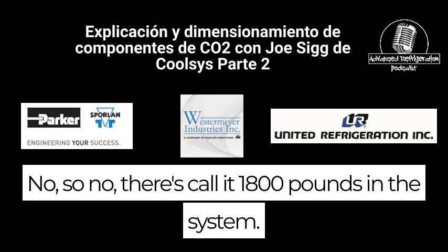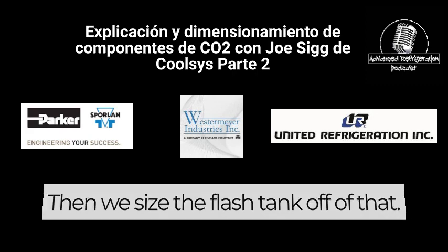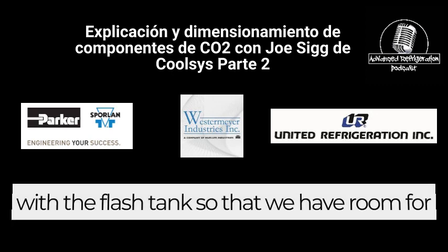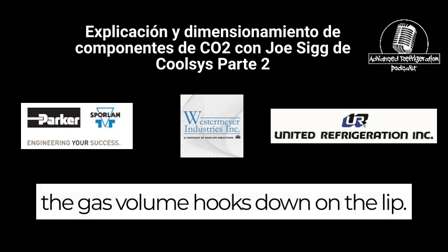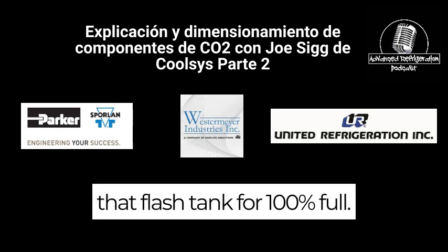No, there's 1,800 pounds in the system, and then we size the flash tank off of that. We know that we want to be roughly 40% oversized with the flash tank, so that we have room for the gas volume to push down on the liquid, basically. We don't want to size that flash tank for 100% full.